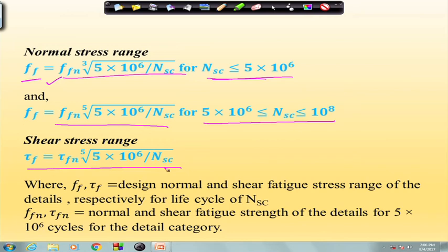In a gantry girder, what we could see is that it is basically a laterally unsupported beam, which needs to be designed for both vertical load and lateral load. We have seen here that a certain percentage of load will be considered as lateral load, and also a certain percentage of load will be calculated as impact load. So, we can calculate the impact load and lateral load, and then find out the total load vertically and horizontally.